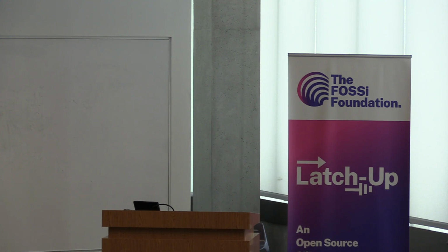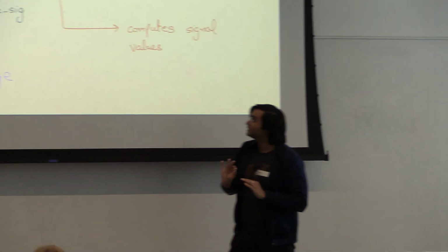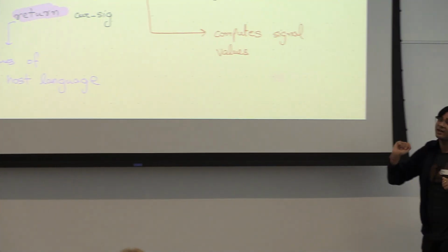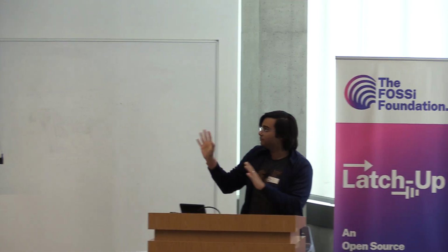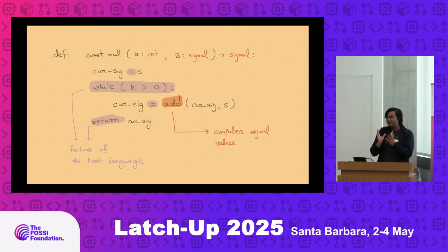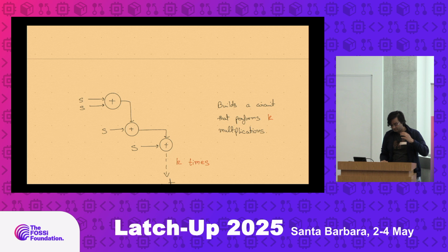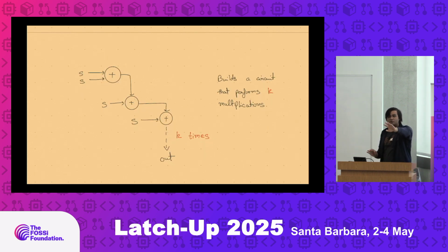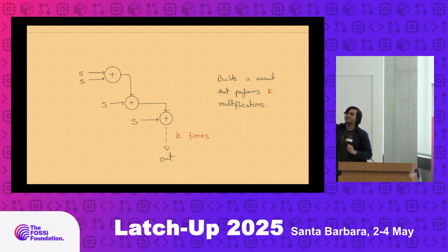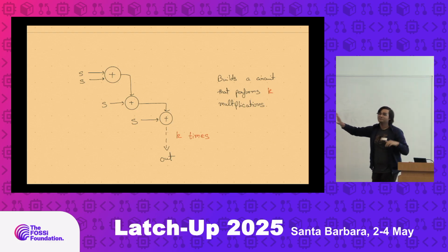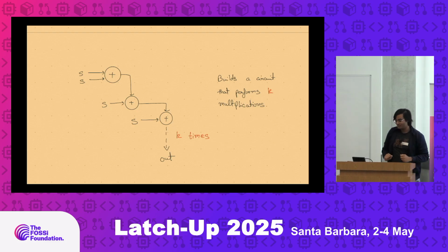You could be Scala, and that's what Chisel is, although Chisel does it slightly differently, I think. And you could do it with OCaml, which is what I've not shown you, but that's what happens in Hardcaml. So the big point to take away from this is that eHDLs, there's some sort of recipe going on in building one of these. I think your answer was getting at this, which is that the circuit we're building looks something like this. It's sort of a chain of, and the critical path is going to be terrible. You're right, right? So this is a bad circuit, but it's a circuit nonetheless, and you can build better circuits potentially. So this is what it computes.